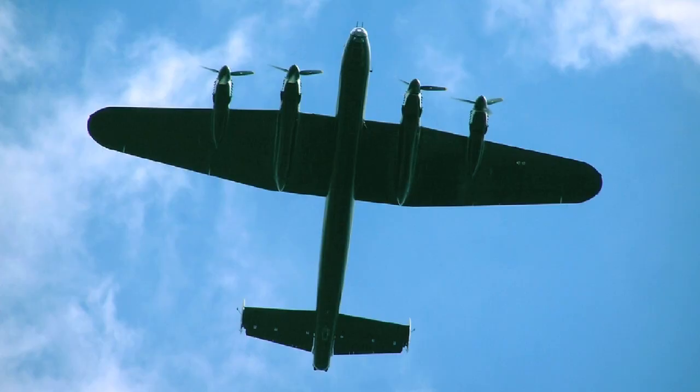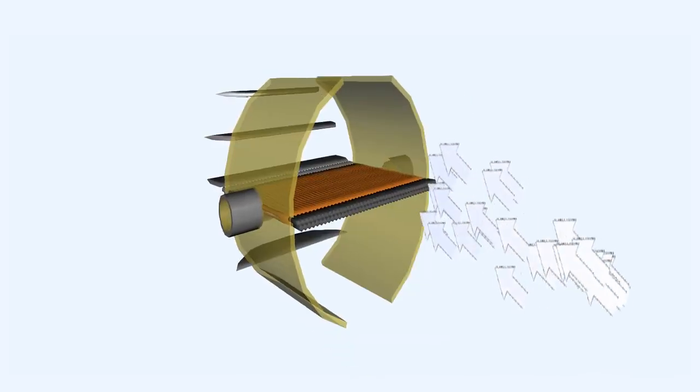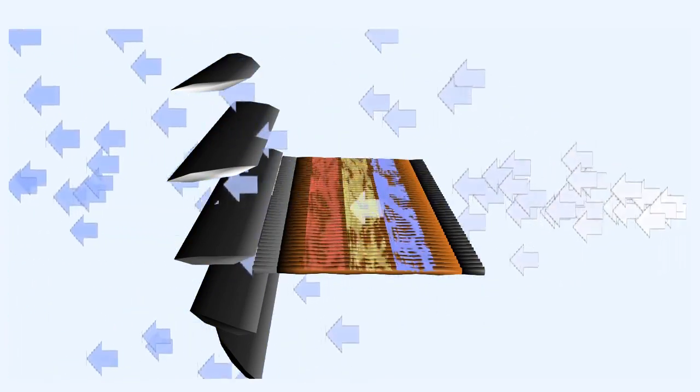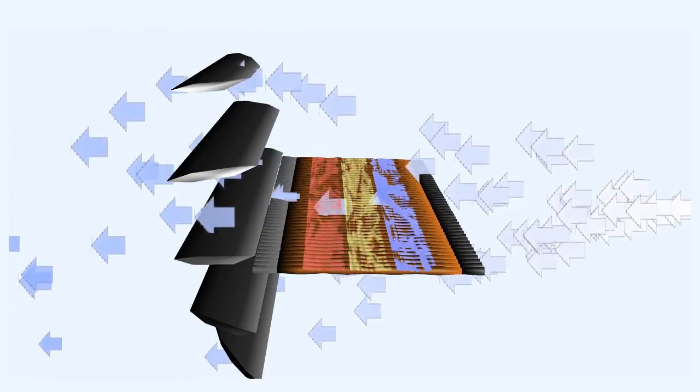Coring is a condition which can occur in engines which are capable of developing very high power outputs. During the climb to height, inexperienced operators would sometimes tend to set the oil cooler shutters in a fairly open position to ensure that the oil temperature stayed cooler rather than hotter. Unfortunately, if the ambient temperature fell faster than anticipated during the climb, the oil temperature would fall lower and lower. The viscosity of the oil flowing through the oil cooler would rise, and eventually the oil would become so thick that in the front of the cooler the oil would stop flowing altogether.